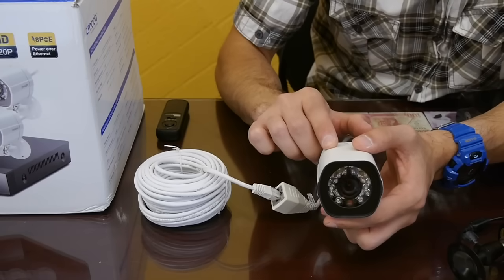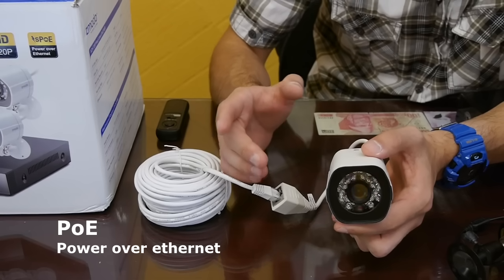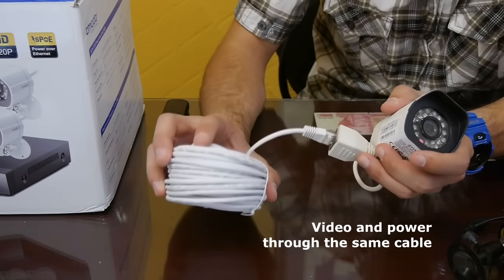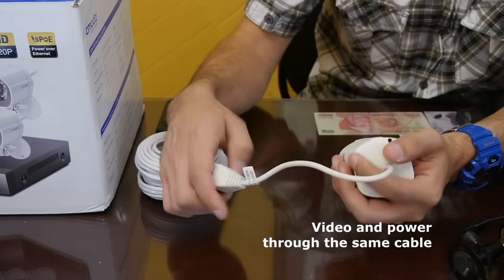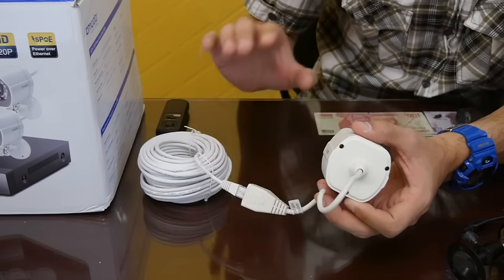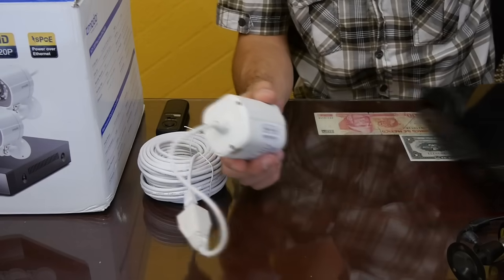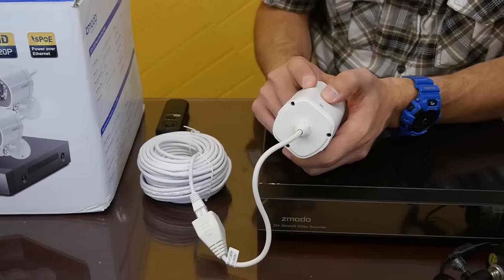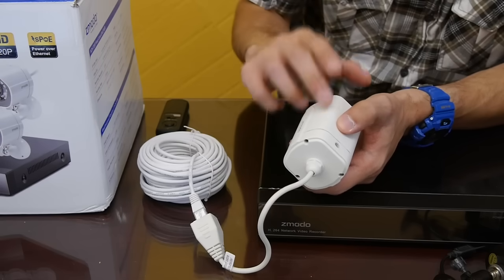Some IP camera systems have what's called PoE, which stands for Power over Ethernet, and it transfers the video signal and feeds the power to the camera all using the same network cable. This camera here is a Power over Ethernet camera, and notice how only one cable hookup comes out of the camera. In order to take advantage of Power over Ethernet, you'll need IP cameras with Power over Ethernet, and you'll also need a video recorder with Power over Ethernet to supply each camera with power. There are also adapters to feed Power over Ethernet cables on regular IP cameras, so you can use one cable instead of two.